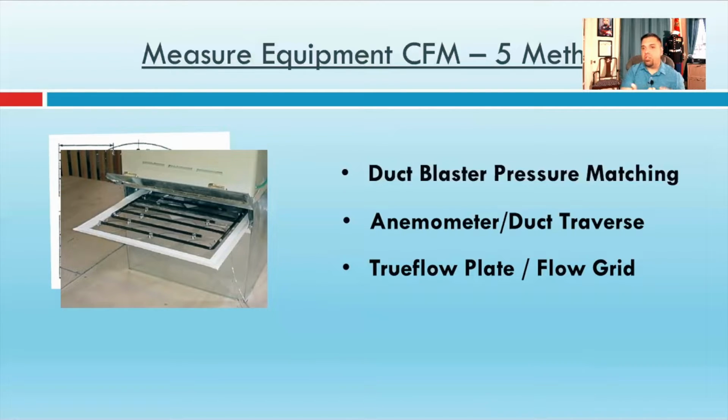It's so fast and easy, and every time I slid that in, I got the same number, and the person next to me would get the same number all the way through when we were teaching these. So highly recommend a TrueFlow plate. It's a little expensive, but very, very useful, because you could be out there on a service call measuring airflow. Obviously, we're talking about testing and balancing new systems here today, but that doesn't mean you don't recommission existing systems. If you don't have all the paperwork, don't get me wrong, there's a lot of stuff available on Google, but if you can't find it, this will still give you volume of air.